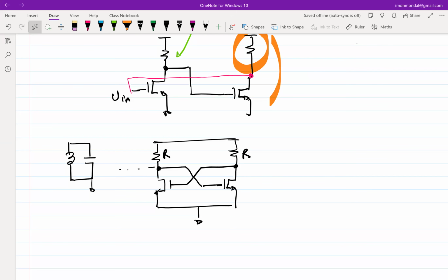If you say that I want a tunnel diode, it means I probably will not be able to use the same type of lithographic techniques, the same masks, to build the new device. I want some additional mask, and every mask is hugely expensive, so it can even double or triple your cost. That is one of the reasons tunnel diodes are not used.